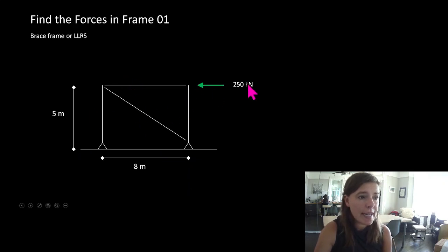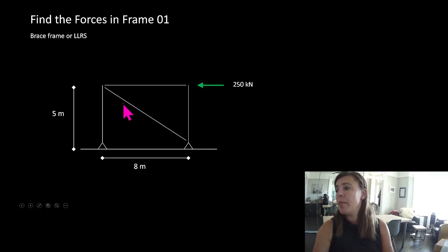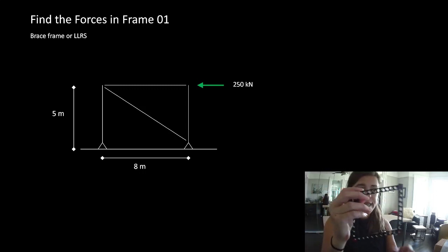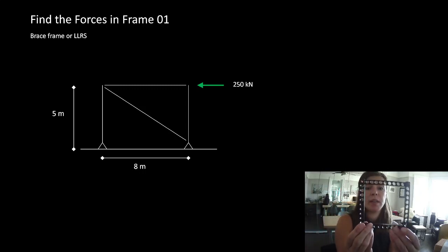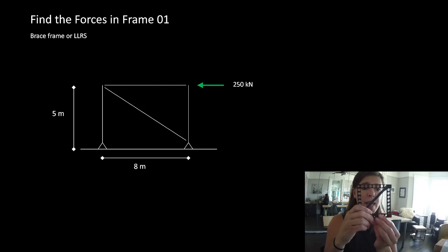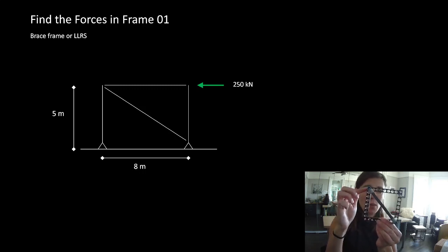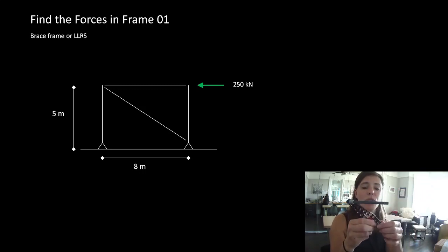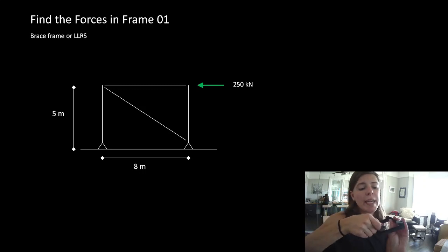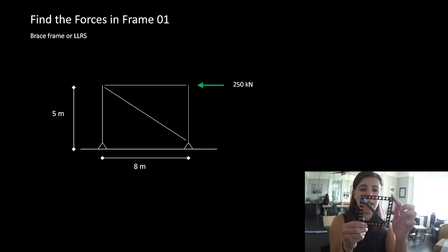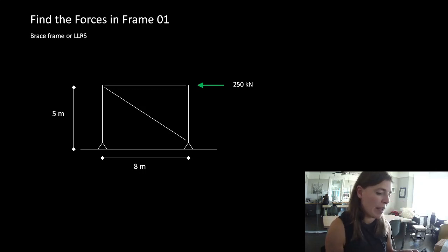So this truss right here, it's actually a braced frame. If you guys remember, I talked about how if we had this sitting here like this and we put a load on it, it would try to collapse. It would flop over. If we put this brace element in it, when we try to push on it, it doesn't try to tip over. Or if we push on it on this side, it now doesn't, unless it breaks. But we needed this here. You can see that this slipped out of here. It was in tension. And I think intuitively you understand that, but we need that element to stop this whole thing from collapsing.